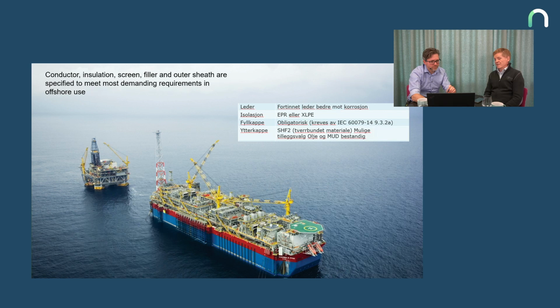Now we can also have silicone insulation in some cases. In the old days, we also had the PVC insulation. It was terrible with the corrosive smoke during fire and poisonous black smoke. So that was never accepted in the NEK 606. And when it comes to this inner covering, that is what I mentioned, the extruded inner covering to make it semi-gas tight.